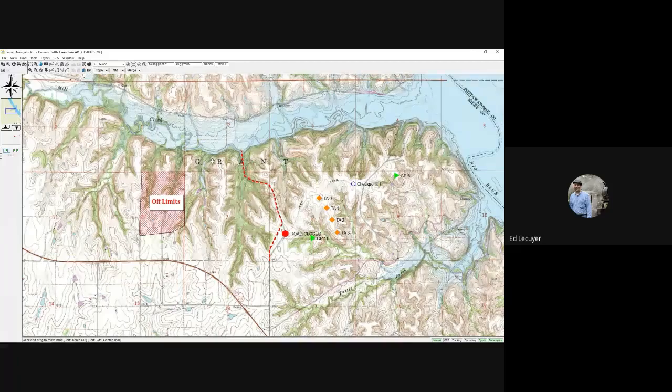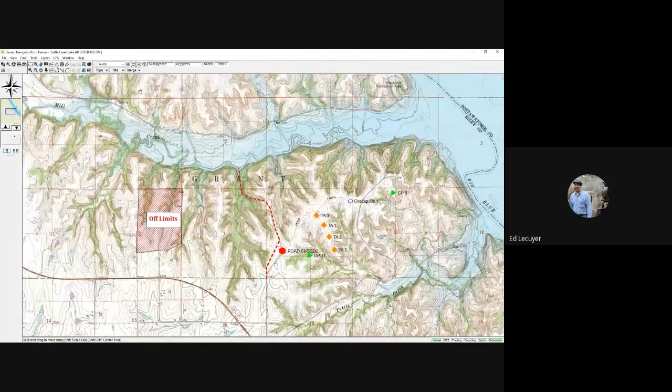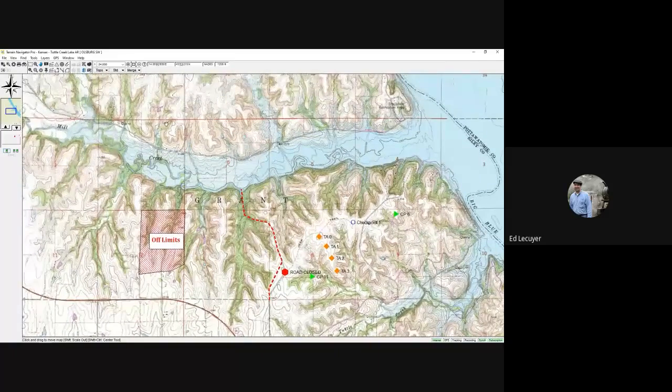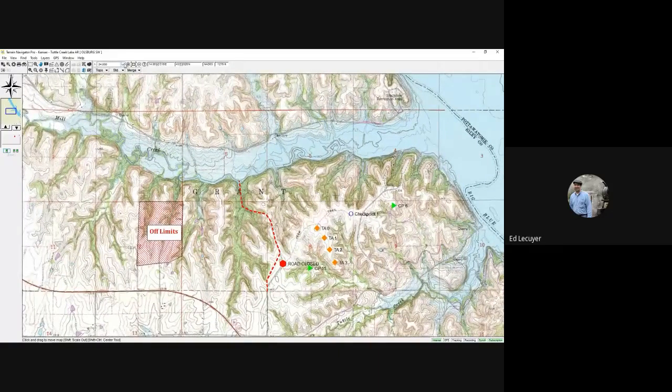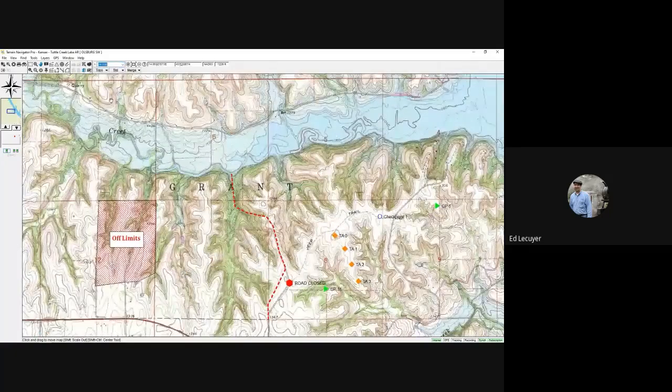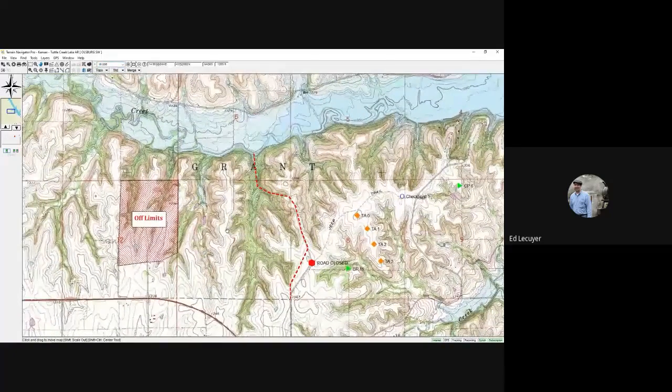And you'll also notice you'll get a performance hit, because when you scroll around, Terrain Navigator Pro has to do a little bit more math as far as how to scale the map to that particular scale. So in general, when you're looking at the map scales at the top, you stick to the default scales, but then when you go to print or export, then you want to put in whatever scale you want. And that's probably more than you ever wanted to know about scales in Terrain Navigator Pro.